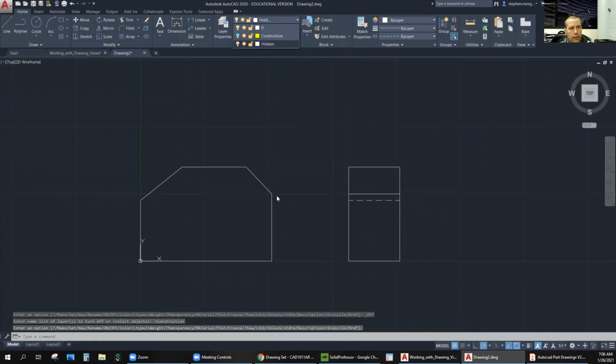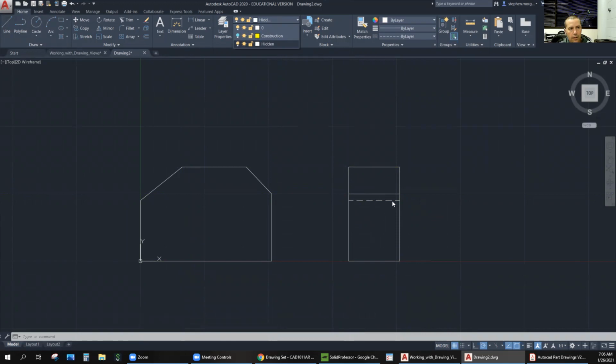And what you're going to see is you're going to get a visible line and a hidden line. So the hidden line represents this edge back here that you wouldn't be able to see because you're looking at this block from this direction right here. This edge is clearly visible, which is that. The other two hidden lines are going to relate to your circle. So let's just throw in a circle. This is not going to be in the correct position.